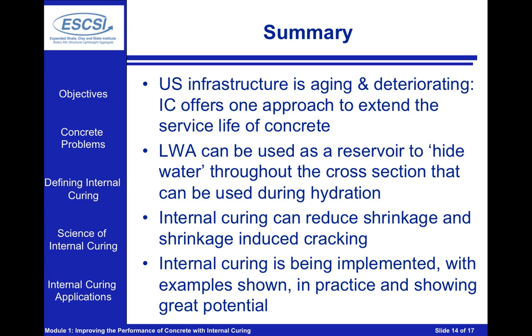Internal curing is done by using a lightweight aggregate, and that lightweight aggregate can be used as a reservoir to hide water throughout the cross-section of our concrete, and by hiding this water we're able to release that water at the appropriate time to increase the hydration of the cement, but also to reduce the shrinkage and shrinkage cracking that may be occurring, especially at very early ages.